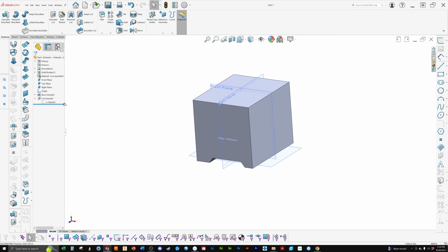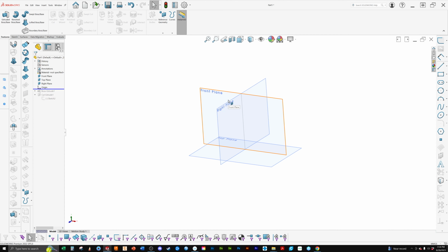So, SolidWorks, and I think you guys recognize this when you were doing it, is massive on planes. You need a plane to do almost everything until we start getting into what's known as 3D splines and things of that nature. But you can see where everything is, you draw it 2D flat, and then you extrude, you loft, you revolve, but it all starts with the sketch.